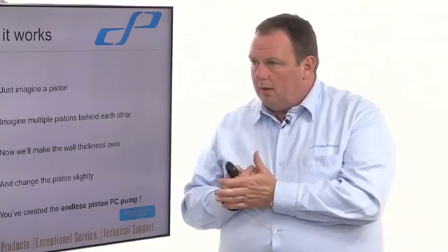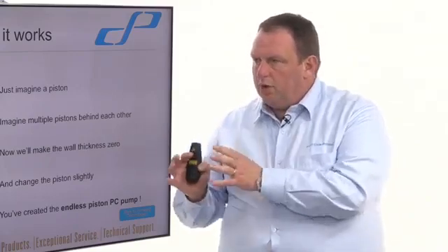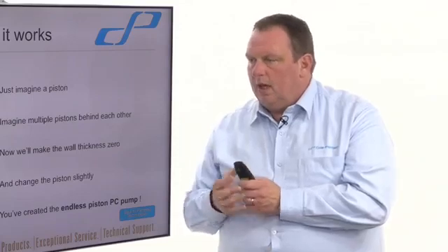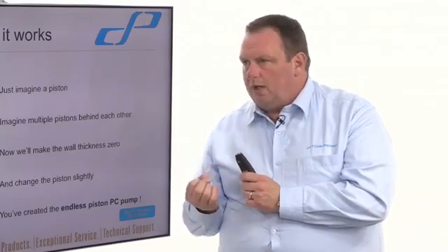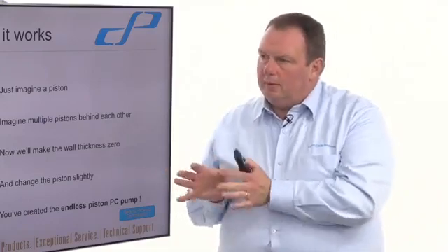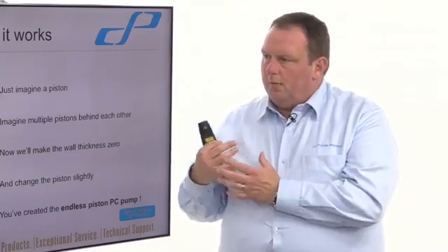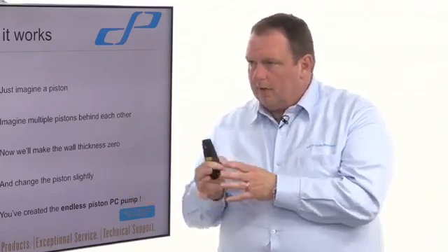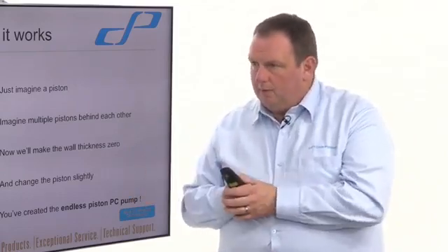It would pull it in, and then you can push it to where you need, whether you're filling little pots and things like that. But you can move an abrasive and a thick slurry with these pumps. That's talking about foodstuffs. Because they're also low shear, they win on the foodstuffs, they can win on other valuable products.